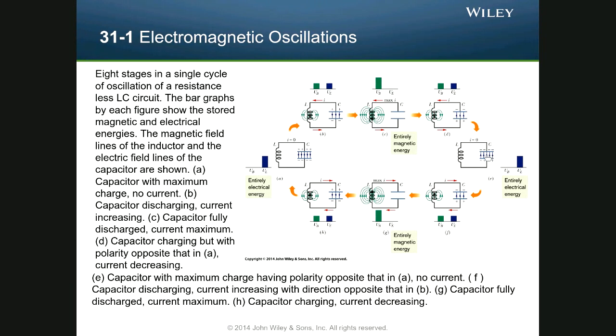However, you'll notice that as the capacitor discharges this time, it will do so with the current in the opposite direction, right? So the current will now go clockwise around the circuit. And then again, as that current changes, you'll lose energy in the capacitor, and that will transfer to the inductor, right? And then after that long time, the current will still flow, and you'll notice the field directions have been reversed as we go through. You can use our convention for electrostatic fields and Lenz's law for the opposing current in the inductor.